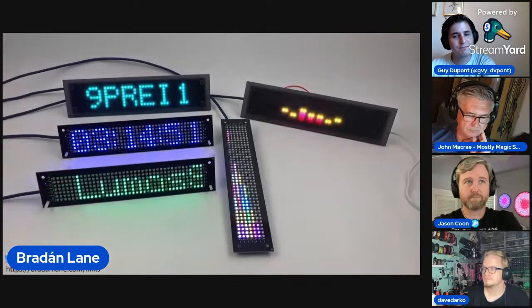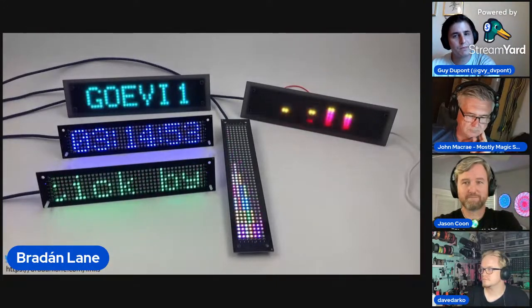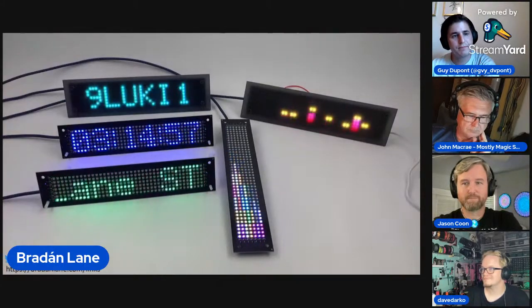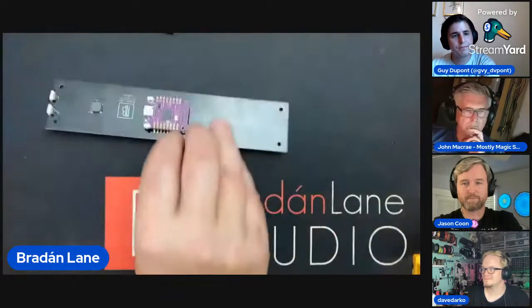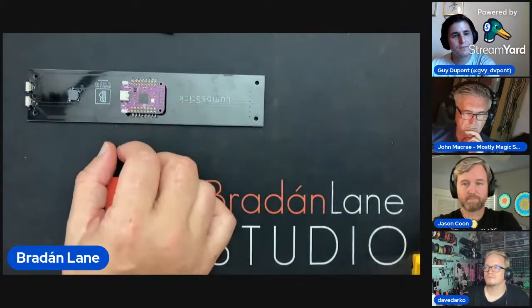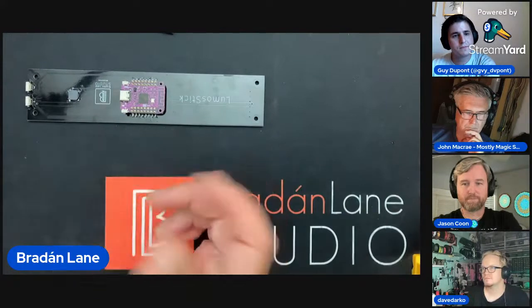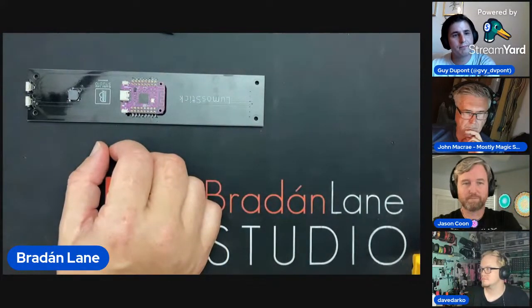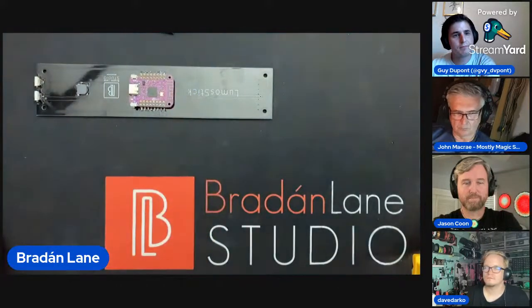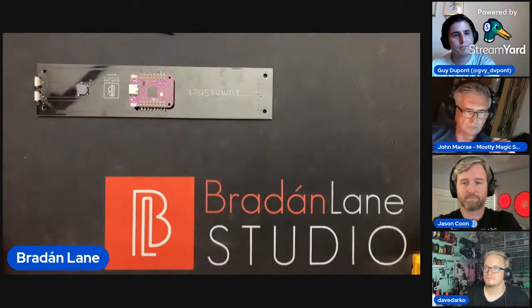Because the module has Wi-Fi, it's an ESP32S2. So if we look at this right here, this little ESP32S2 gives you Wi-Fi capability, so you can hook it up to the internet and you could pull text from something and scroll it. So a tweet could be scrolled. I just use it for grabbing the internet time to display the clock and have it update automatically.